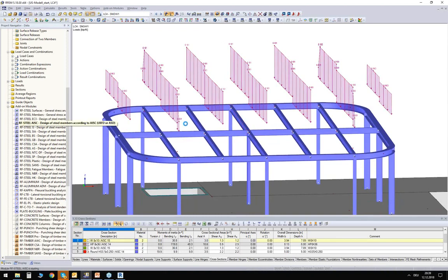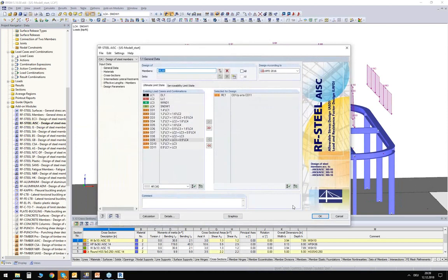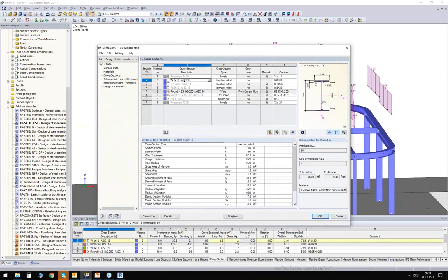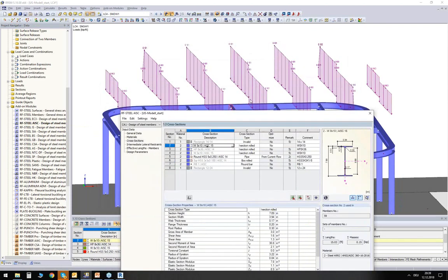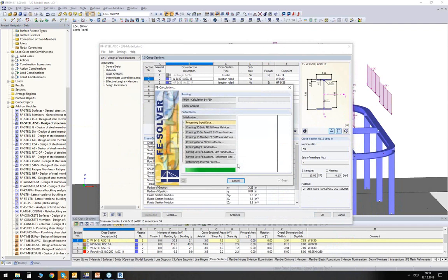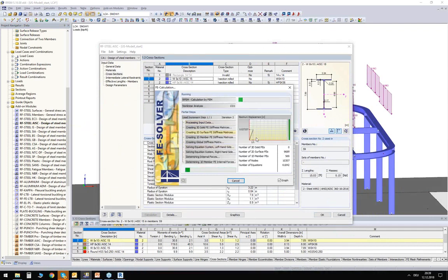This basically means that the load on the beam we design will be reduced. So I go back to my module, and I rerun the design. For the pipe section, I'm using an automatic optimization, and for this section, I optimize the analytical structure in the background. I click on calculate again. And of course, I have to recalculate the internal forces now, simply because I changed the analytical model in the background. I added additional beams and redistributed my loads, so I have to rerun the analysis.